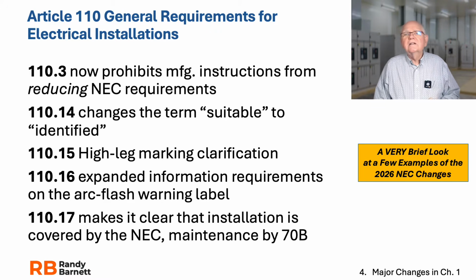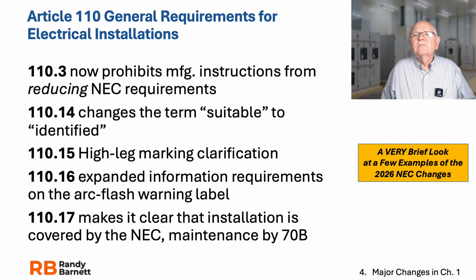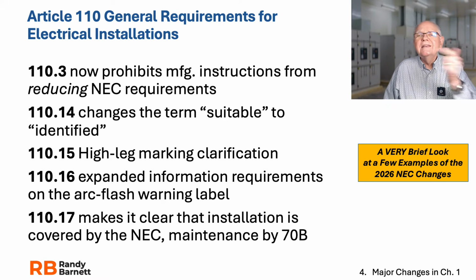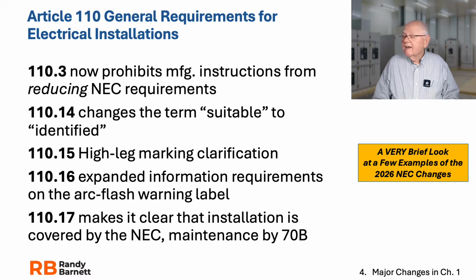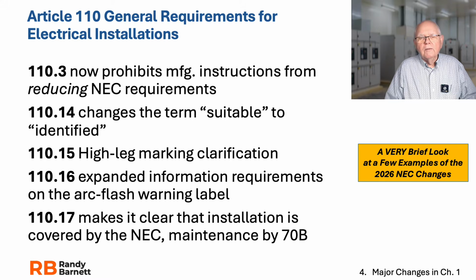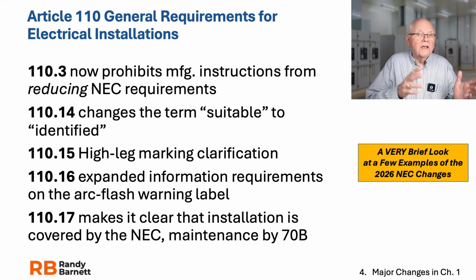110.17 now makes it clear that the installation is covered by the NEC, but maintenance is covered by 70B. So that people somehow don't get confused. In fact, I had a phone call earlier this morning. A fellow called me up from overseas asking about maintenance requirements in the NEC. We don't address maintenance in the NEC other than right at the beginning back there in Article 90, right, where there's some explanation about assuming we're going to maintain our equipment to keep it safe.